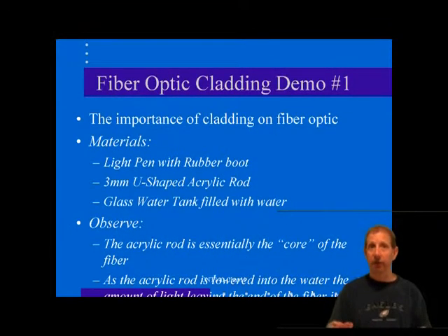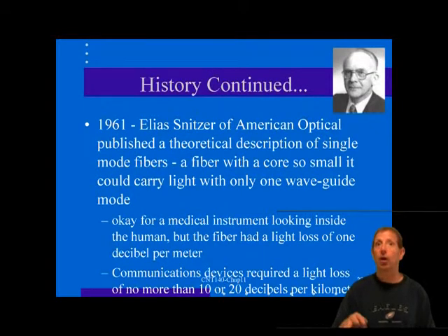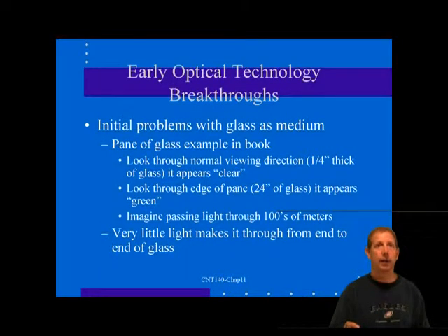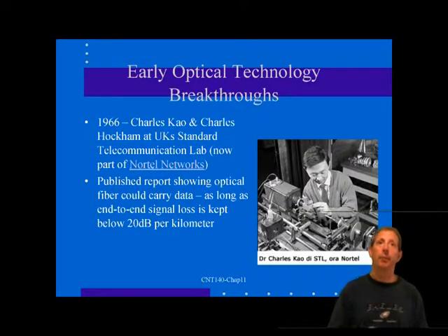In the case of the laser sources, the light beam is already quite collimated and must simply be aimed accurately at the fiber core. As a matter of fact, the coupling of the optical source and the interconnection of the terminated fibers are critical parts of fiber optic transmission technology. If the termination is properly done, the connector hardware will normally ensure that the fiber-to-fiber or fiber-to-source coupling is maximally effective, resulting in an absolute minimum coupling loss.